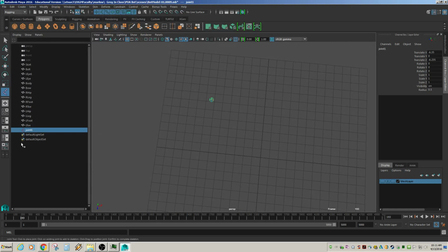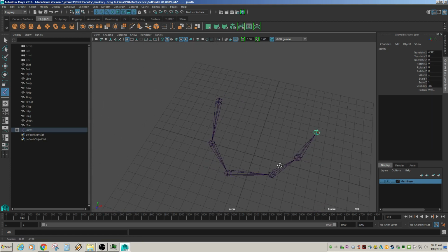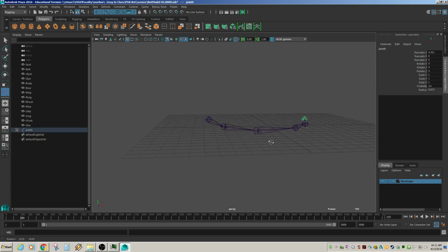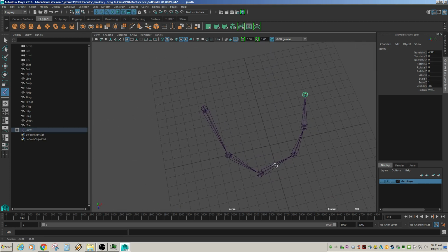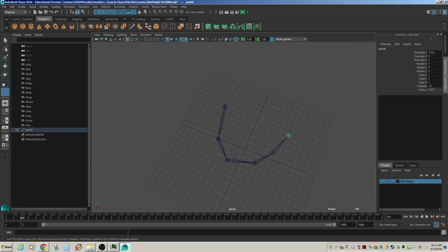And you'll see it's joint 1, and when you look over here, you'll see it has a different icon from the mesh. And so if I start clicking while that's selected, it will add another joint, and it will connect those two. Now my second joint is selected, and so I can just sort of create a quick joint chain. By default, the creation of this joint chain is going to look for some sort of axis to constrain it to, and you'll see that what it's chosen was just the grid, which was a good choice in this case. Now, whenever I'm ready, I can hit enter, and now I have a full joint chain that is completely editable.